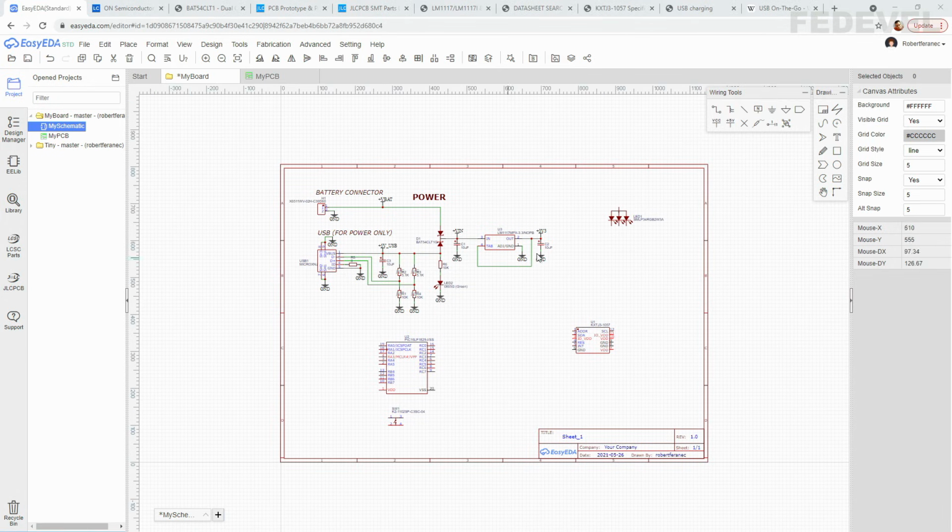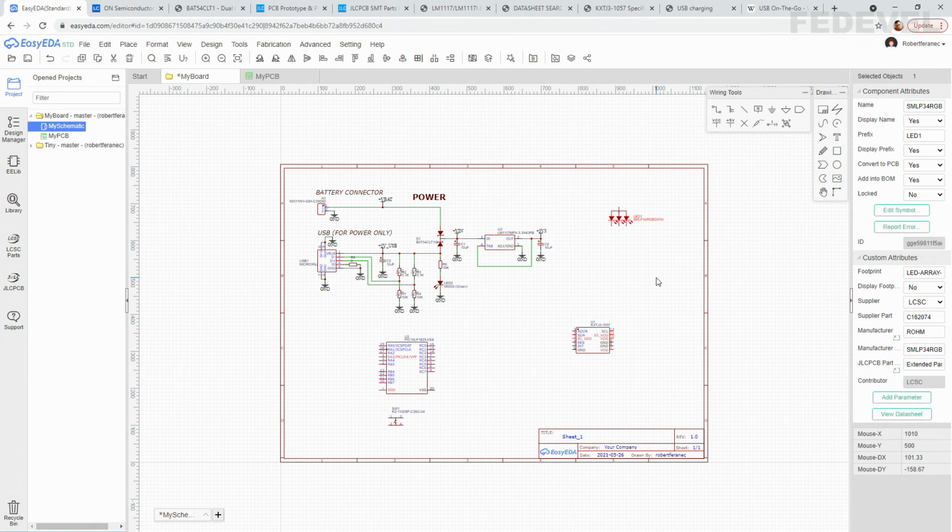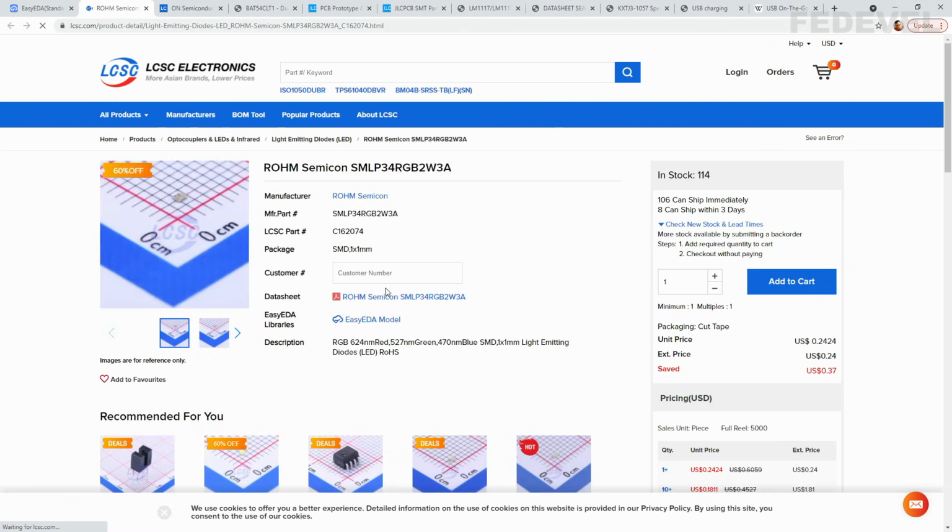Next, we are going to connect this LED, and to limit currents flowing through these LEDs, we need to put here some resistors. And as I promised, we are going to learn how to calculate the value of these resistors, which we would like to use together with an LED. Select our LED. We would like to see the datasheet. So left click on View Datasheet. Open Datasheet.